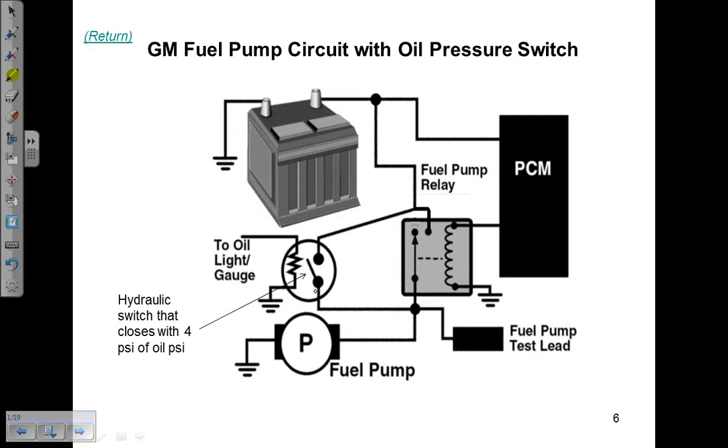A lot of people think that this oil pressure switch, which is right here, is here to shut the engine off if the oil pressure gets too low. That's completely false. That is not why it's there. We are not trying to protect the engine with this oil pressure switch. If you look at the circuit, what you will see is this is a parallel branch to the fuel pump relay circuit. It's not a series branch, it's parallel.